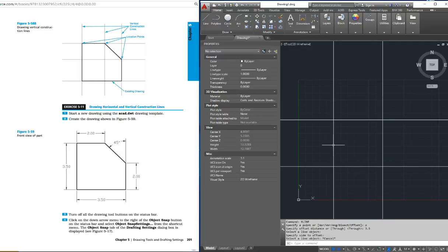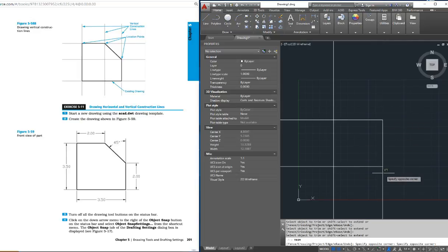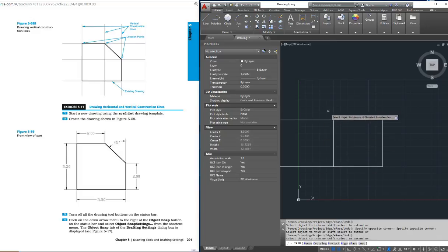Now you can see I have this box is where my shape is going to fit in. So if you remember from the other ones, you can use the trim command right here, or I just like to type TR, trim, enter, and you can just pick all the lines you want to be shorter. And they'll get short. Now I just have my box to work with.